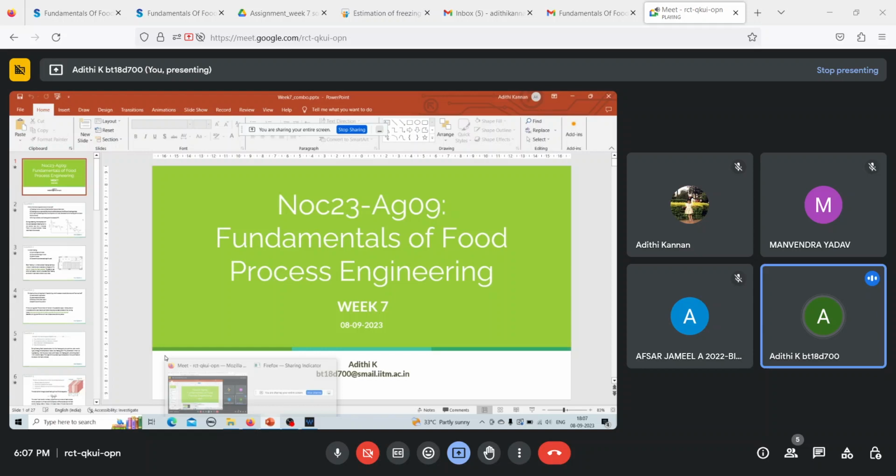Generally, there is an equation that has been found, with which you can calculate the mean freezing temperature if you know the temperature at which you are operating the freezer and the final temperature that you want. So Tfm is equal to 1.8 plus 0.263 Tc, where Tc is the final temperature of the food product in the center, plus 0.105 Ta, which is the temperature of the cold air being blasted in the freezer. With this we can calculate Tfm. We already know the rest of the parameters: the density, the specific heat, Ti, and Tc. We will calculate Tfm and then delta H1 and delta H2.